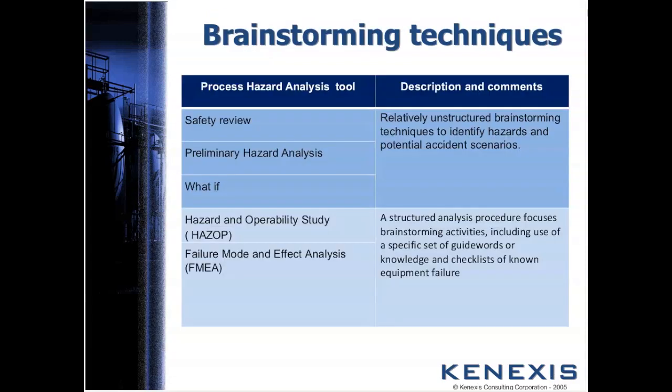Brainstorming technique. Had a little brainstorm right there. There are a number of different techniques we're going to chat about here. Safety reviews, preliminary hazard analysis, and what-if, which are relatively unstructured, as I've denoted here. And then you've got some stuff that's more structured, the HAZOPs and the FMEAs.